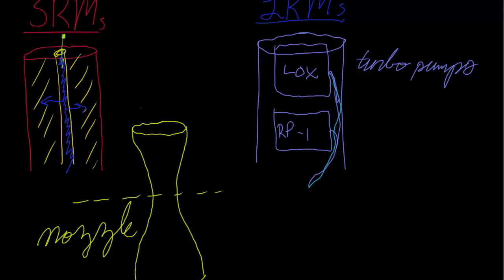So once they get to the rocket nozzle, they get pre-mixed with something called an injector plate. An injector plate is basically just a round plate that looks kind of like a shower head. It has a lot of holes in it, and it premixes our RP1 and our liquid oxygen right before they catch on fire and combust. Once they combust, they're pushed into our combustion chamber, the top piece of our rocket nozzle.